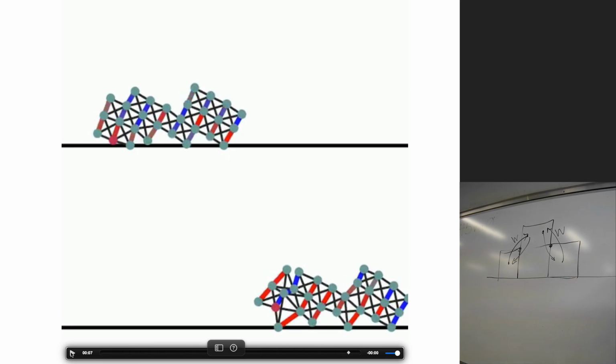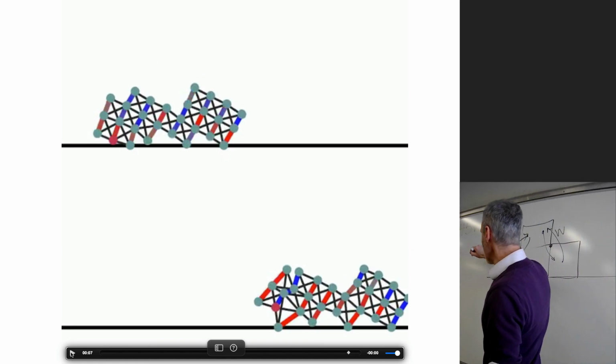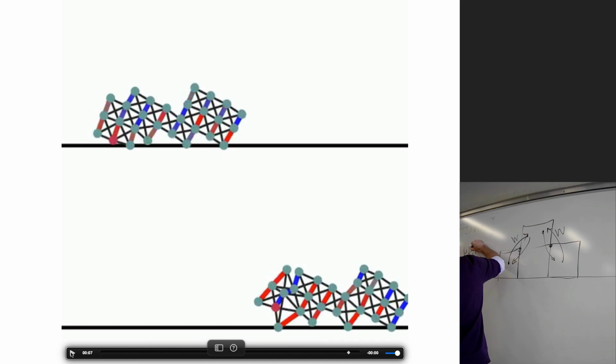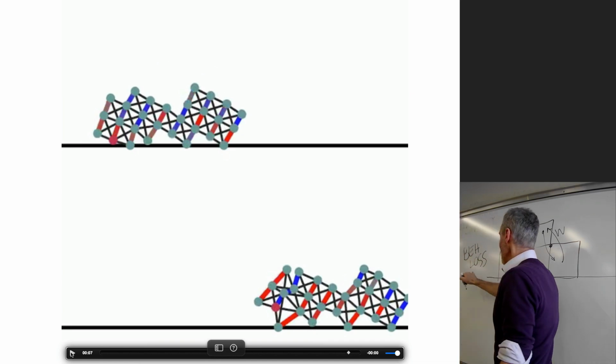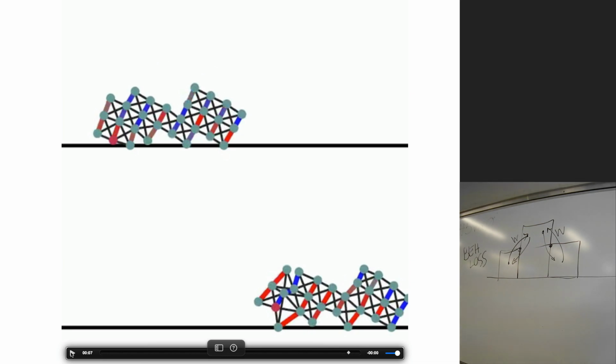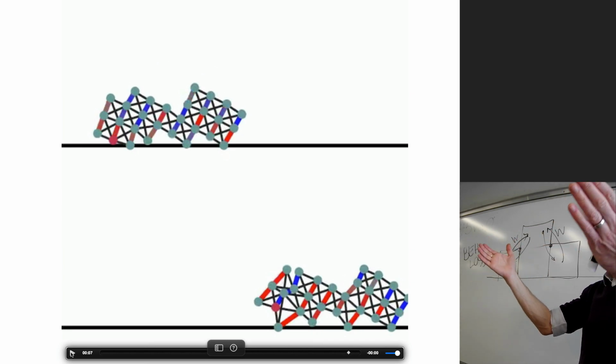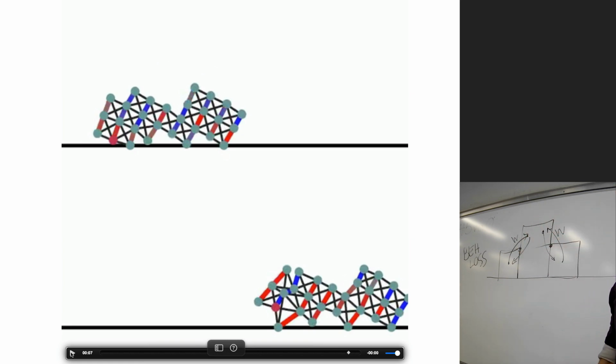Instead of maximizing distance to the right, we're going to pick some target location to the right. We want the robot to get here, T for target location. We then give the physics engine not a fitness function, but a behavioral loss function. In machine learning, we often refer to loss and trying to minimize loss. There's some inefficiency or errors that our potential solution is exhibiting, and we want to minimize those errors or minimize loss. When we're talking about robots, we're going to try and minimize behavioral loss.